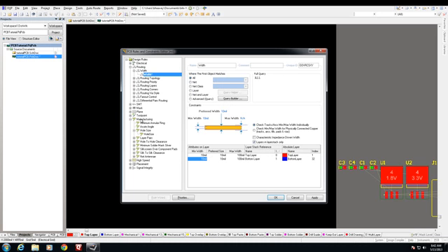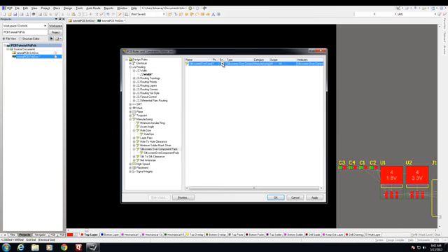The next thing that we're going to need to change is under manufacturing. Here we have some silkscreen elements, the yellow lines that are within the package of our footprint, which is causing errors. It's not actually a problem in our PCB, so we're going to go ahead and disable this rule by clicking on the silkscreen over component pads entry and then unchecking the box.